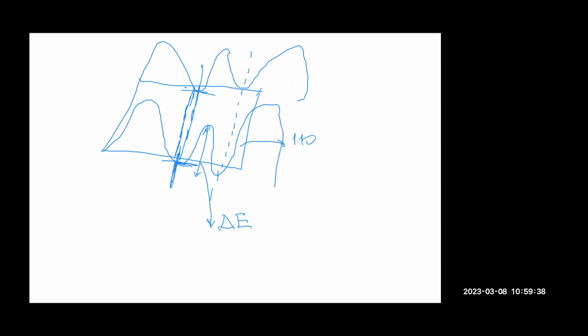That is why you don't have dislocation activity until maybe 400 or 500 megapascal. That is why they are very strong. Once you plot their stress and strain, you will see that BCCs are very strong, but they do not possess significant ductility. You cannot activate the dislocations easily. You need to overcome this energy barrier.